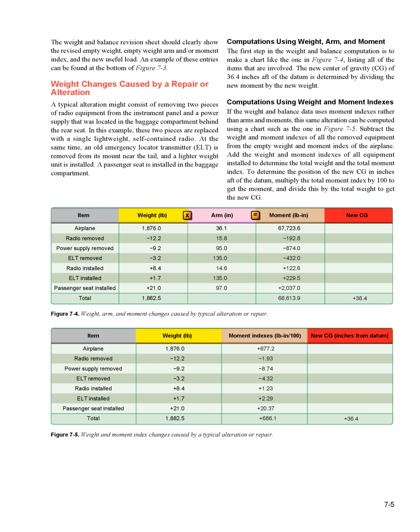The weight and balance revision sheet should clearly show the revised empty weight, arm and/or moment index, and the new useful load. An example of these entries can be found at the bottom of Figure 7.3.